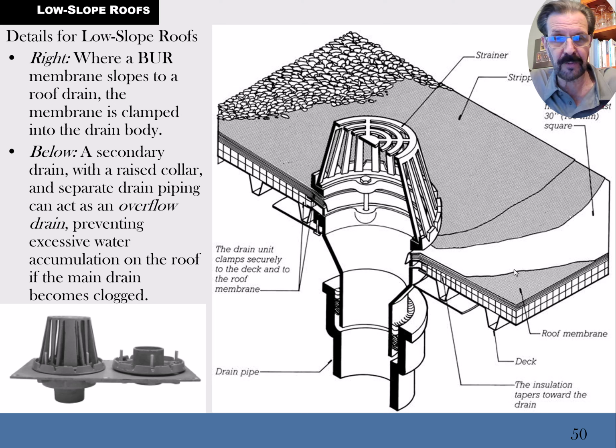And one of them had some kind of water leak going on, but it turned out the problem was that even though it's 4 stories up, there were some rubber balls up on that roof that had gotten there, I guess, because kids were bouncing balls against the side of the building, and some of them were accidentally getting up on the roof. And one of them had made a pretty nice cork to clog that. There was a strainer missing, and the rubber ball was literally corking the drain and causing a whole bunch of water on that roof. And so it's a good thing I went when I did, to pull that thing and drain that out.